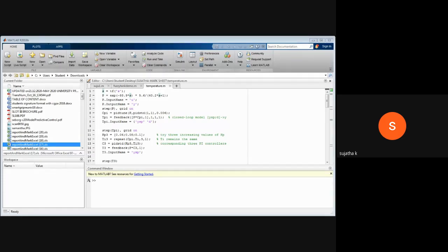Okay. So I took the constant block and I have included it here. Now I want to change the value. To change the value, double click on the same block. When you double click, the block parameters open. In this you can change the value. I will make it 22. I am just fixing the value for this constant block to be 22.